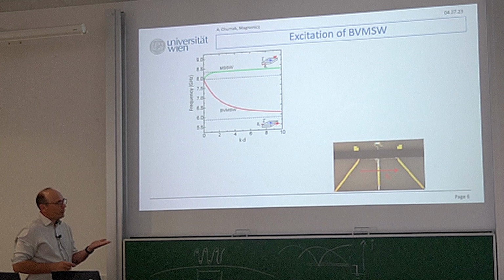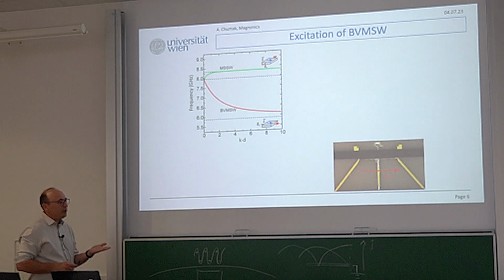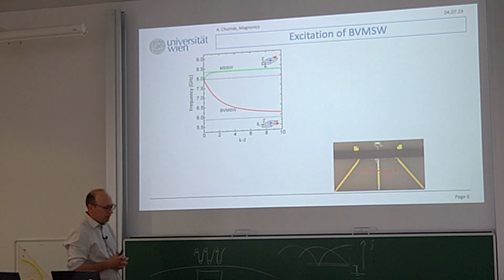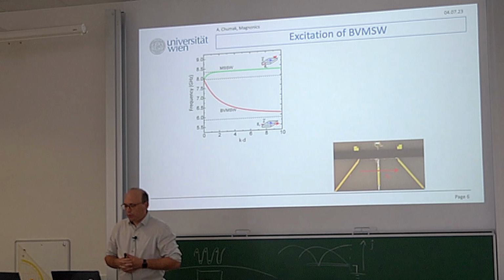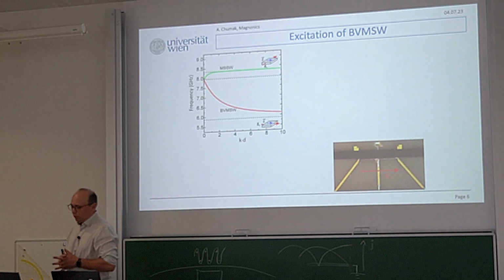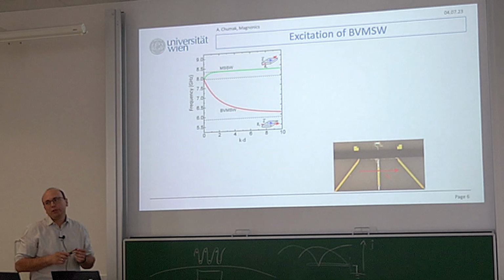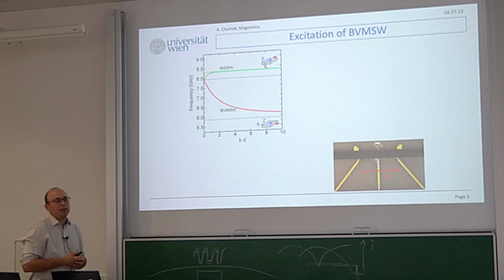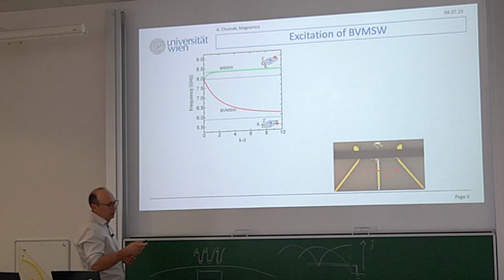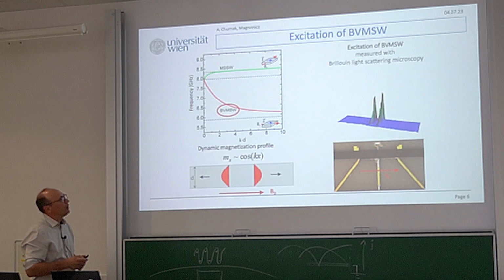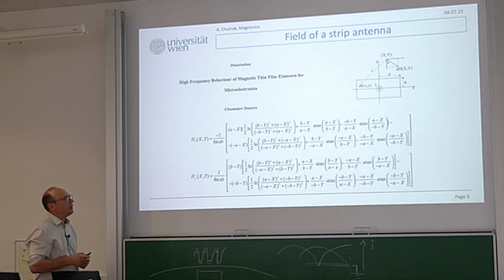And when you do the same at the nanoscale, then it usually works differently. You do not have this flip structure, but you deposit antennas directly on yttrium iron garnet. Antennas then, of course, are smaller. Usually people work with CPWs also in order to keep 50 ohm matched.